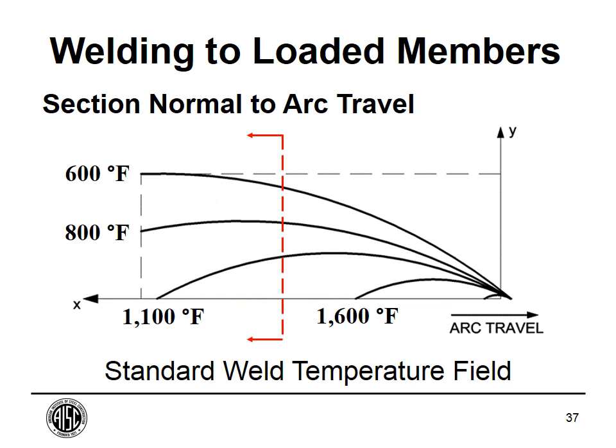This isn't going to answer the question, but you can see what happens as you're moving along in the negative X direction. The weld before adds heat at this cross section, and then when you're at the cross section, it obviously adds a lot of heat along that cross section. And then when you're ahead of that with your arc travel, it also adds heat back here. So it builds up to a maximum, and then it falls down.